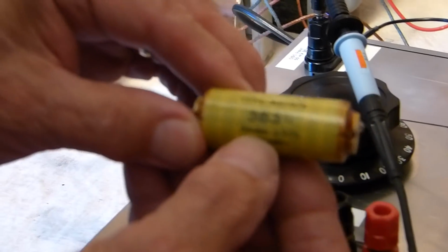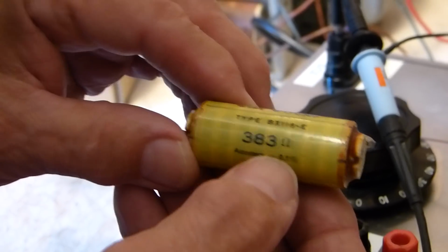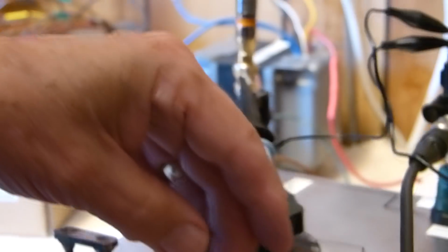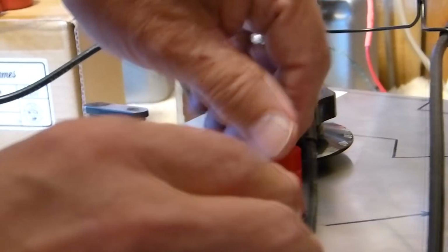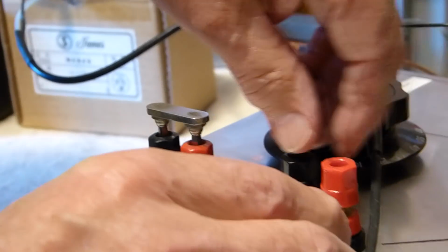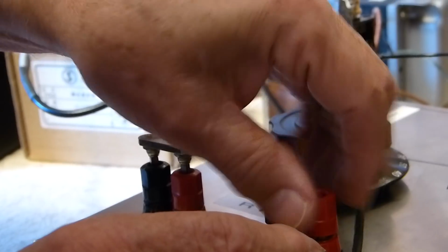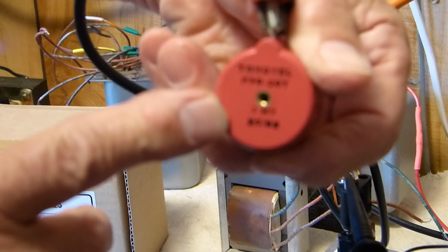See, this one is 383 ohms. It could be 300 ohms, it could be 400 ohms, it doesn't really matter. But if we're going to measure low inductance values, we need a low inductance resistor here. Let me put this in there so we get the right amount of phase shift. So let's measure a standard inductor. Right here's one. That one is 1 Henry. See how close we can get to 1 Henry of it.